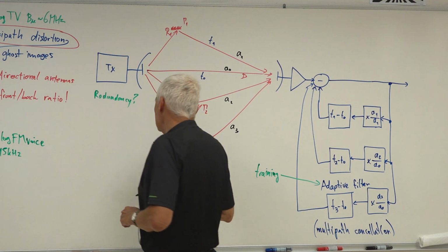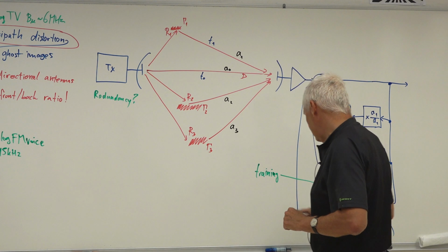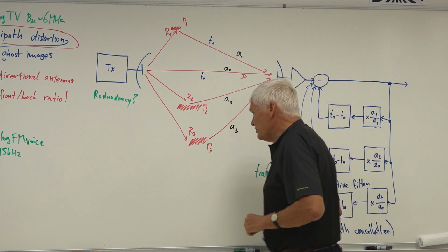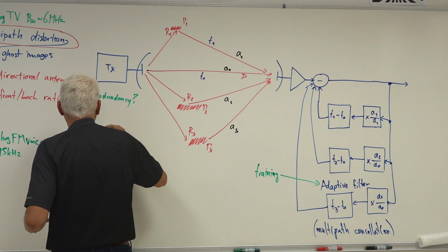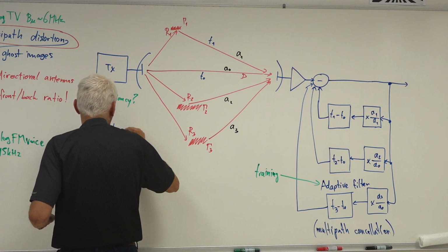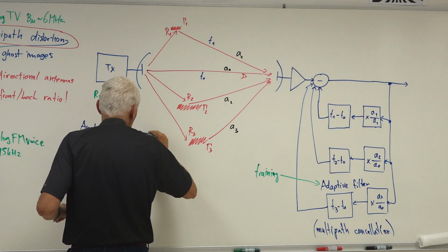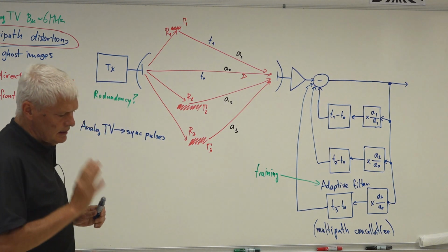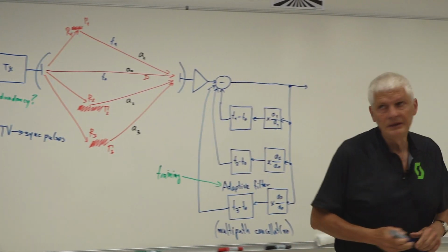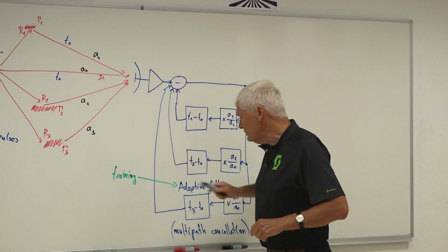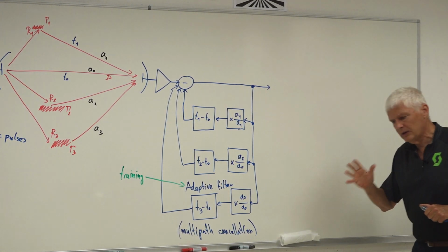In the transmitter, and that redundancy, where may it come from? It may be already present in the signal. For analog television, where the sync passes. Synchronization pulses were always clearly defined in the television standard, so we could teach our receiver to adjust its filters to remove all reflections on the sync signal. We know what the sync signal is.